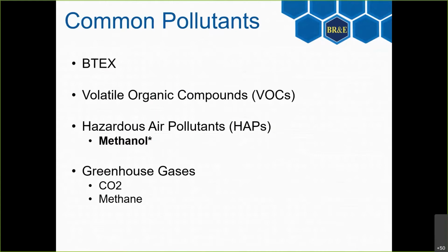Methanol does a good job of deterring that, but it has a pretty strong affinity for being picked up by TEG units at certain conditions. One thing that ProMax does very well is we have a property package strictly dedicated to handling methanol and its interactions with hydrocarbons and water. So this tool can very accurately track methanol in your system as well.